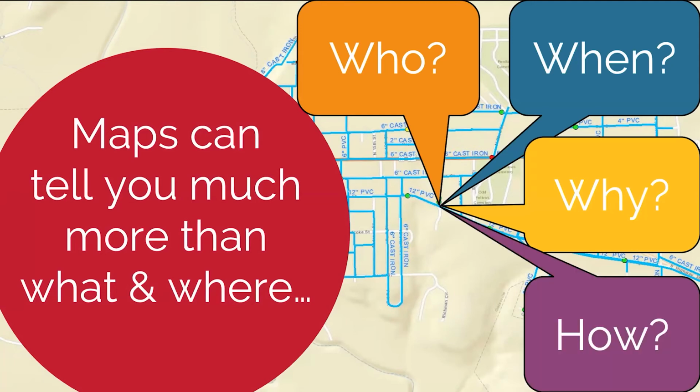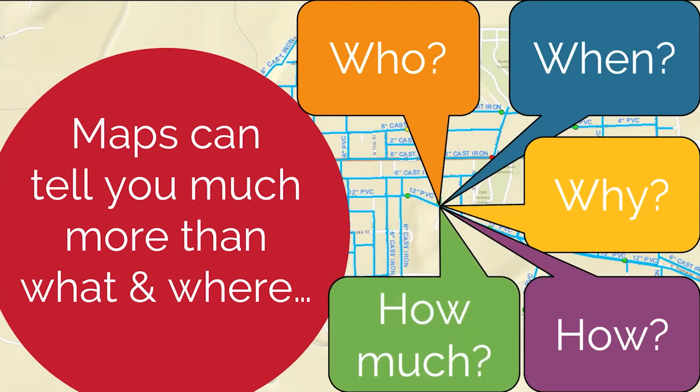So event data, for example, tracking breaks I mentioned earlier, is really important. If you track breaks and include why the break happened, was it a split, was it corrosion, that can give you really useful information. And again, if you've been collecting that replacement cost data I talked about, you can use GIS maps to give you pretty good cost estimates on different kinds of projects.